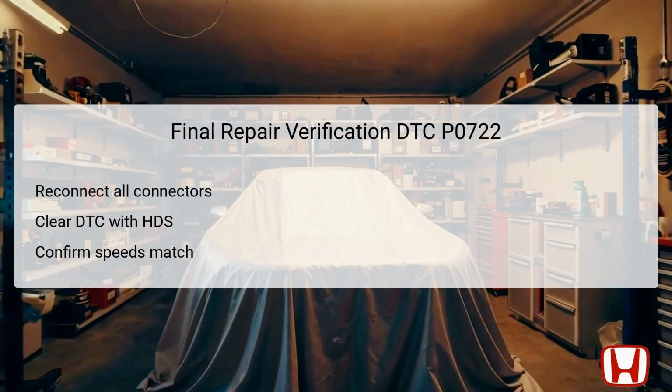Next, turn the ignition switch to the on position and use the HDS to clear the DTC from the system. With the DTC cleared, start the engine and disable VSA using the button as before. Drive the vehicle in D, while observing the speed readings from both the input shaft and output shaft using the HDS. If the speeds align closely, it indicates the issue has been rectified, signaling the completion of the troubleshooting process.